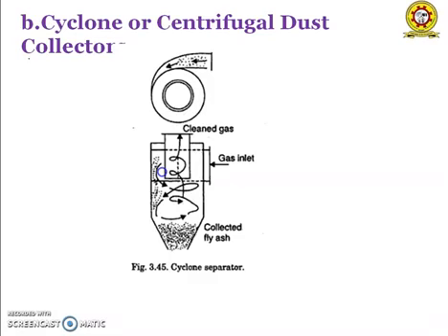Inlets and sufficient velocity head pressures are used to produce this. As multiple small diameter vortices with high pressure drop appear to have good cleaning efficiency, that type is now being exploited. Skimming cyclones shave off the dust at the periphery of the vortex along with a small portion of the gas flow. This concentrated flow is then led to a secondary chamber for the final separation.